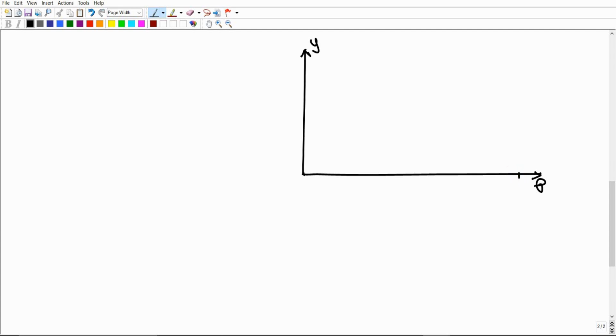Then your objective is just to draw a complete, closed rectangular dash line, in this way. The height of this rectangular dash line should be the total lift, which is already given to us as 50 millimeters. If we decide to work at a 1 to 1 scale, the 50 millimeters is equivalent to 5 centimeters. So I'm gonna measure 5 centimeters over the y-axis, and then mark a point.